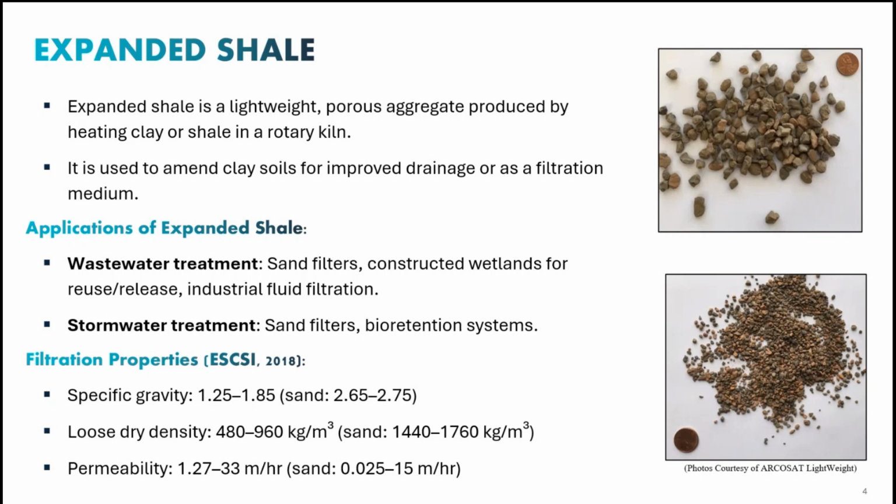Some of the properties of expanded shale we can see here: the specific density of the expanded shale is much smaller than that of the sand, and the permeability is very high compared to the sand, so it is a perfect solution. Probably in our work, we're going to see how that helps us with the design of bioswale. Next slide, please.